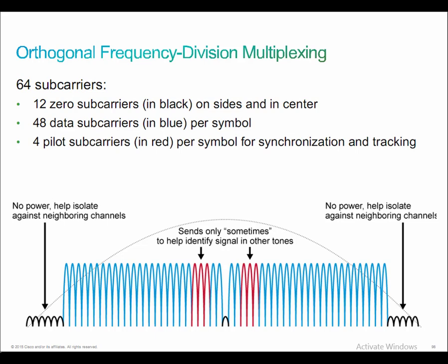So not only is OFDM faster because each channel transmits more slowly, meaning that it has to work less, it bears less density of the symbols per millisecond, it becomes more resistant to multipath distortion. Because there are so many channels, some can be affected by interference, but the others can still offer normal communication.